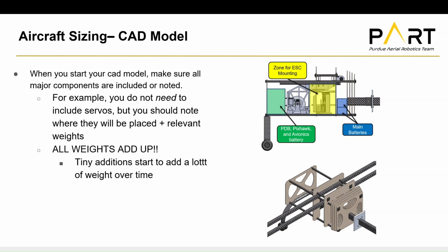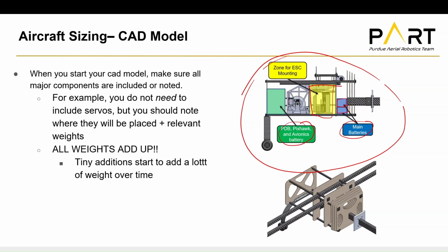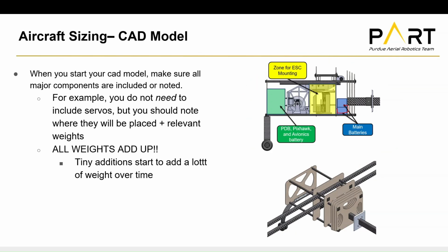So here you can see this is our CAD model. We never showed where our PDB and our Pixhawk and avionics or our batteries are going to go, but we did draw out in a slide this idea so we can see where they would go realistically. And we love mounting our ESCs on the exterior of the fuselage for a bit better cooling. But this way, we don't have to CAD all of that, but we do note where they are so nothing goes forgotten about.